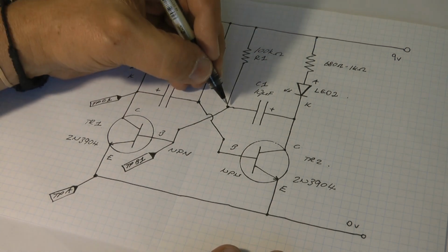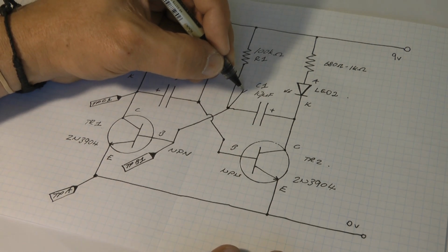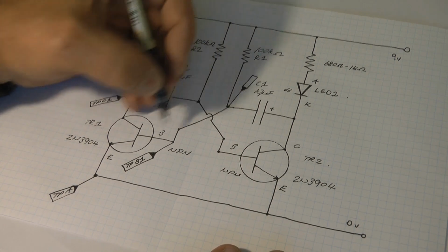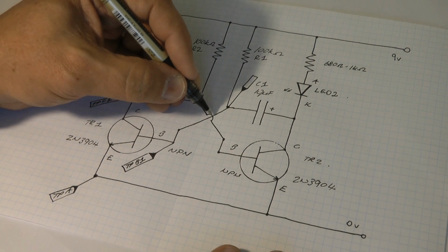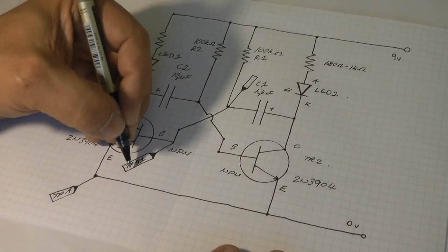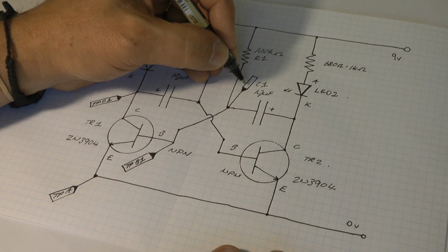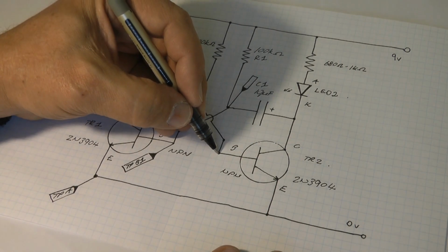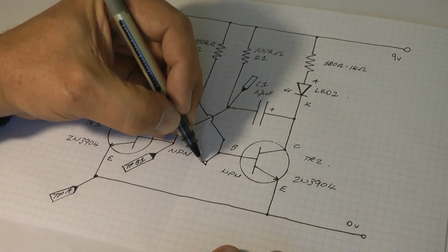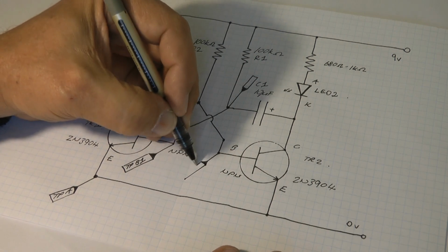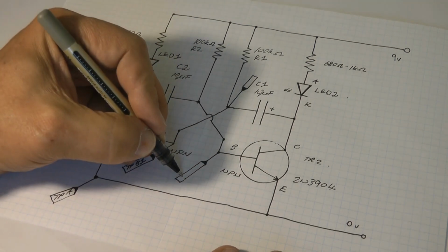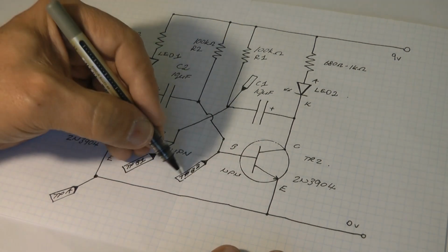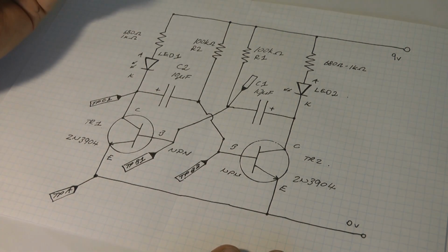Now, by implication, we could attach a test point here, but electrically it should look the same because this is connected to there. So this is also test point B1. So I'm not going to write anything there. Now we can attach our red lead of our multimeter to the circuit over here. And this point would be test point B base 2. So it's test point on the base of transistor 2.